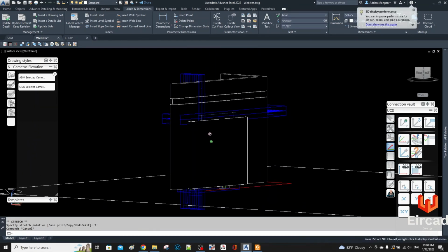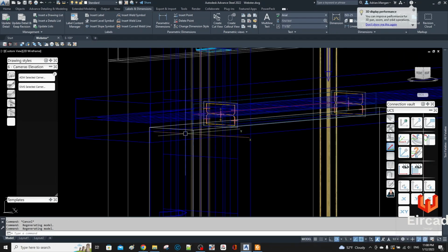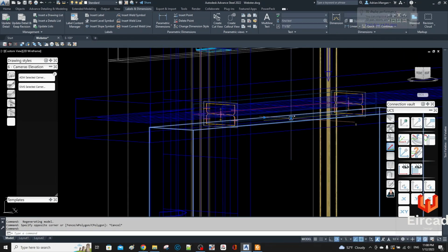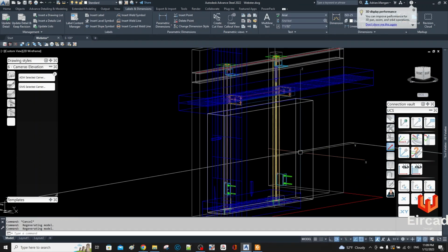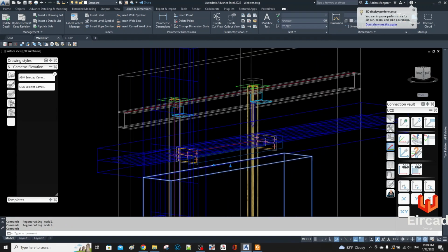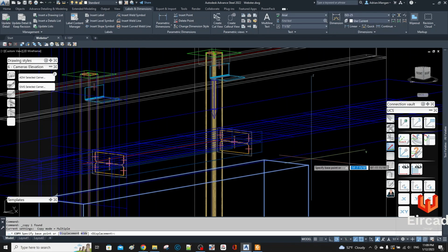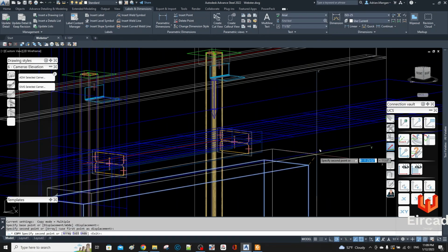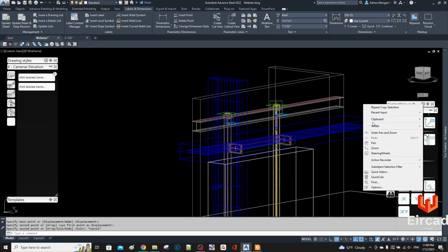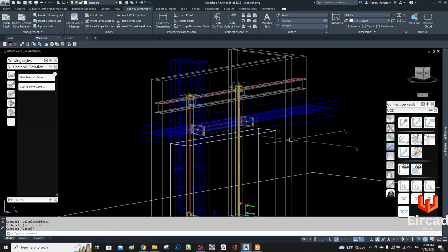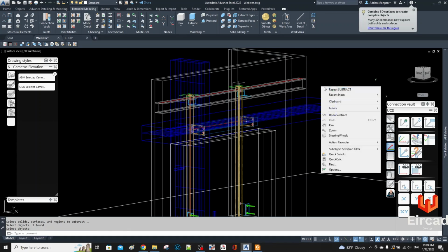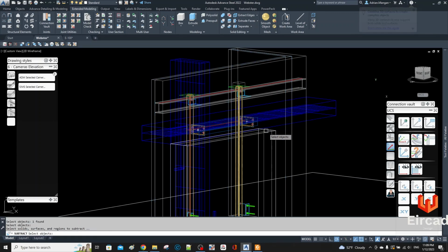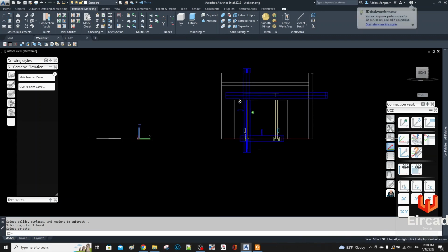Have a look and see how that looks. Is it below the beam? Not really. So we'll take that down 6 inches, so I'll do 6'6". And then I want 2 of these because I have to go through the other wall also. So copy this from here to here. And then isolate, object isolation, and extended modeling. Okay, and repeat subtract. Alright, so there's your opening.